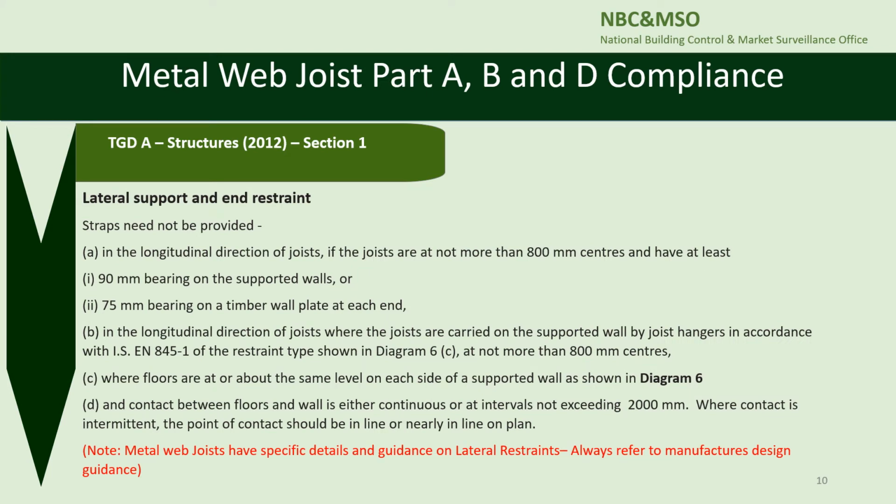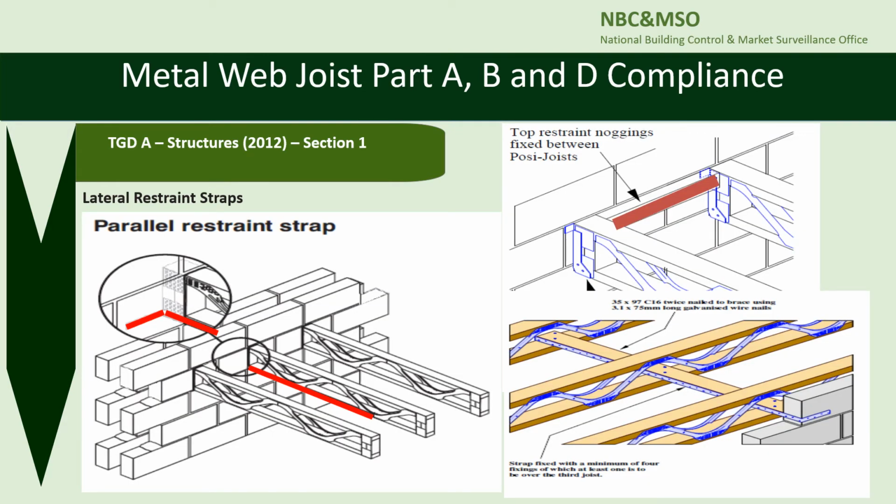The guidance on lateral supports and end restraints, where straps need not be provided in Technical Guidance Document A, is for traditional joists. Designers should seek manufacturer's guidance and manual details on lateral supports and end restraint details. This slide shows lateral support and end restraint details from manufacturer's manuals.